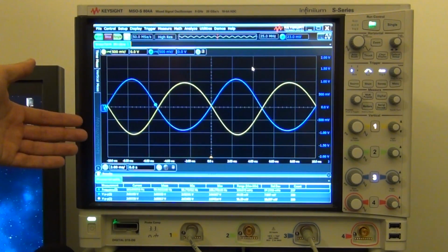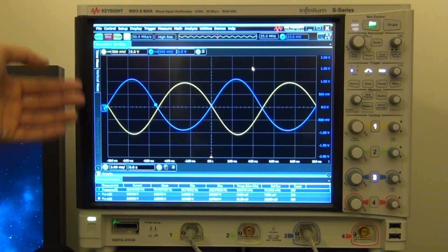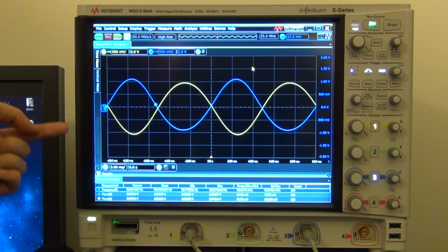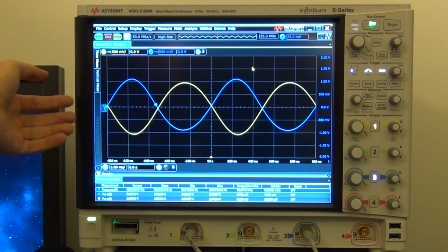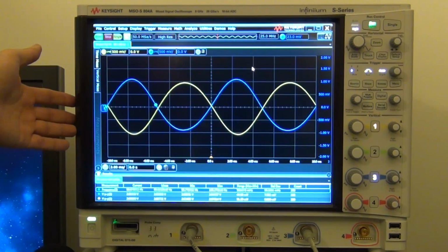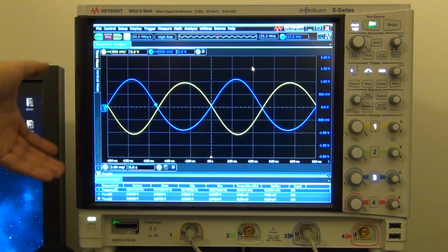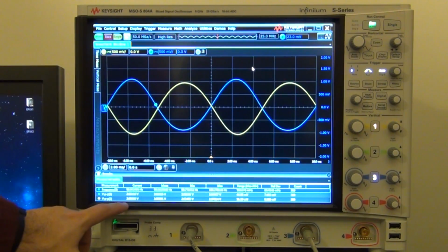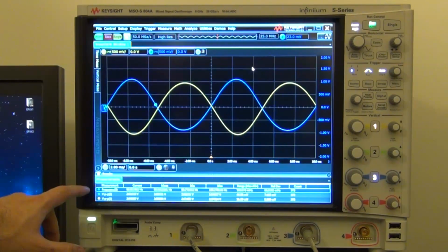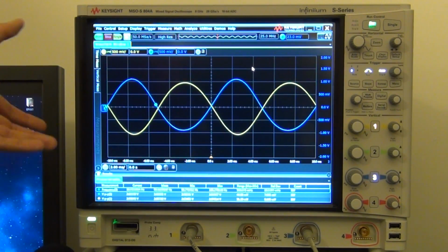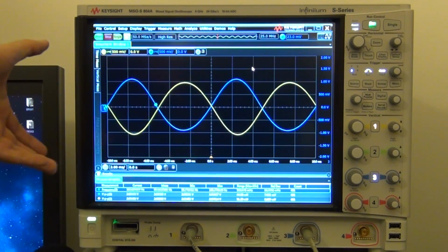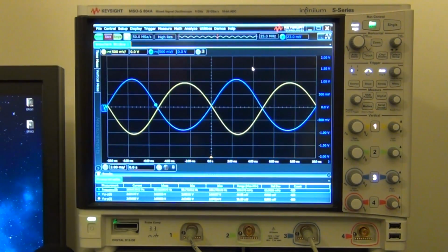And here we finally have both of the waveforms on the oscilloscope. The yellow waveform is the signal we get directly by using the resistor, and the blue waveform is coming from the CMOS transimpedance amplifier. Since both of the resistors are the same, both the resistor in feedback and the resistor we're using as our current to voltage converter, we expect the same amount of gain, and indeed that's the case. You can see these two signals have 2 volt peak to peak of amplitude at a frequency of 100 Hertz. Both of the photodetectors are receiving roughly the same amount of light, so we expect the same signal. So let's go ahead and increase the frequency and actually see what happens.